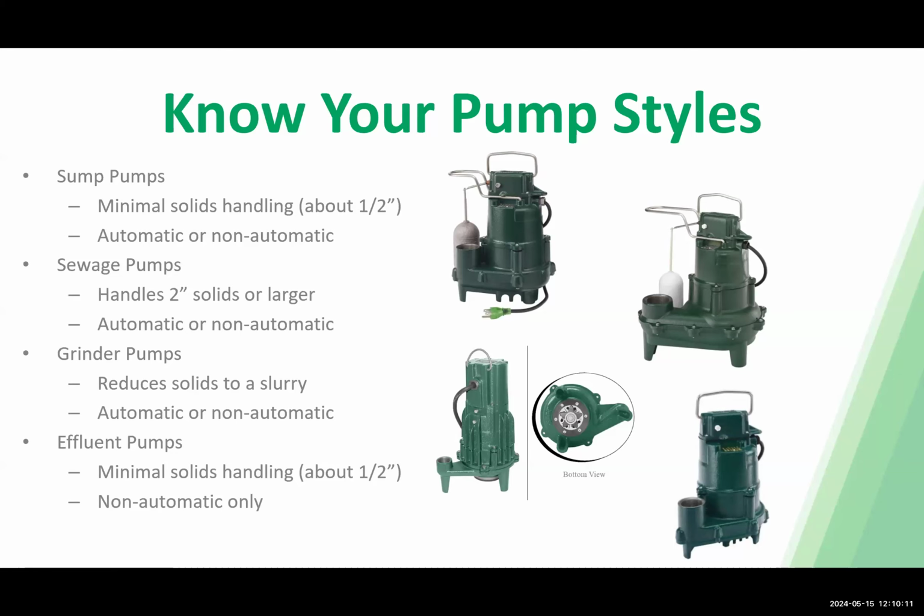They'll eat away at the cast iron. They'll eat away at the seals. So you want to keep that pump submerged at all times. The only way to keep a pump submerged at all times is to have the float switches above the pump. So because of that, that pump will stay submerged in that water at all times.